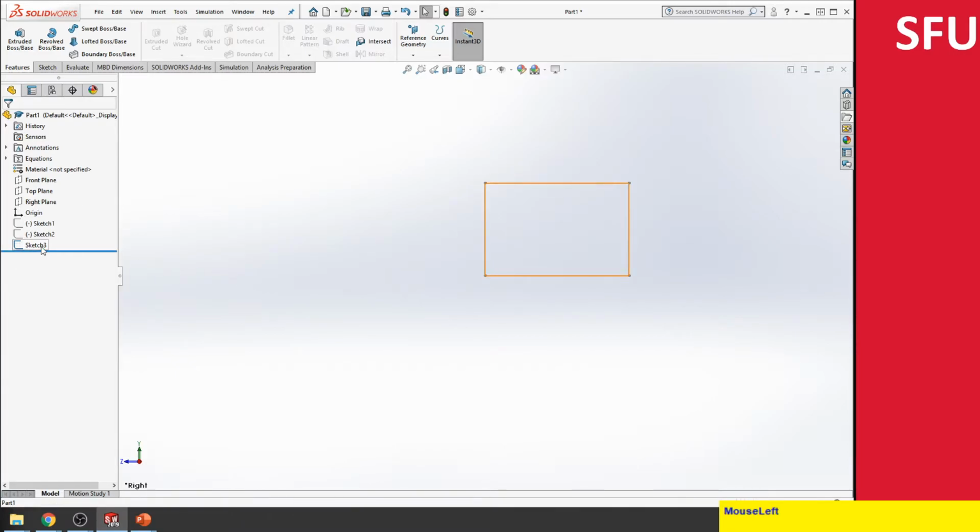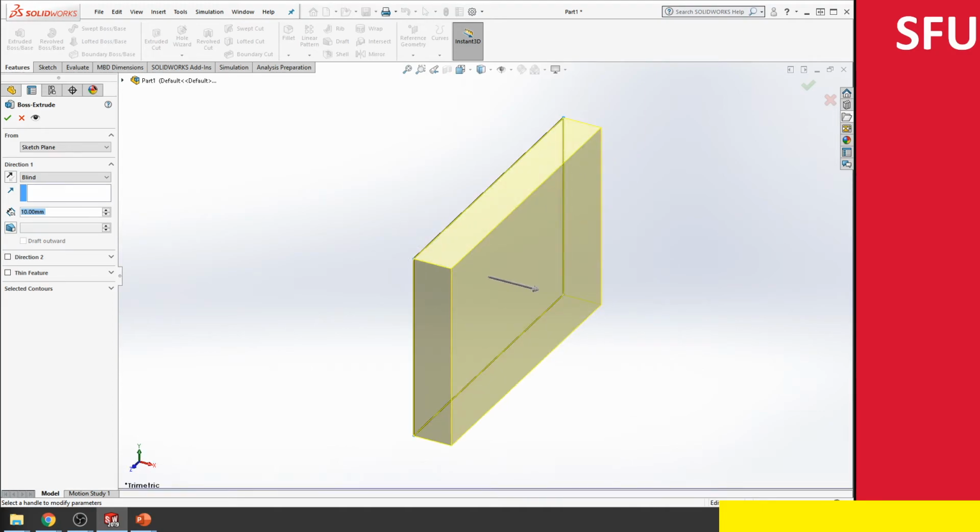Then I can click on the Features bar over here, and if I say extrude, it's going to pull the shape out of the plane, right? Similar to what we discussed. On the side over here you have all of the options that are available. It gives you a detailed preview, but we'll focus on the other things here.